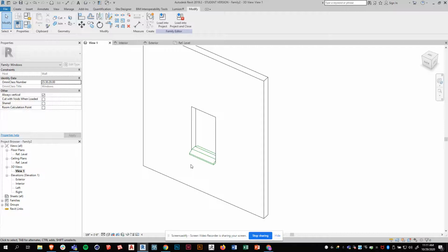Okay, everybody. So in this video, I'm going to do a demonstration of how to use the sweep blend tool. That's essentially this combination of blend and sweep, but in one tool. Now, the annoying thing about this tool is that you can't do a multi-segmented line. It has to be just like one line. And on that one line, then you have two shapes, and basically you go from one shape to the next